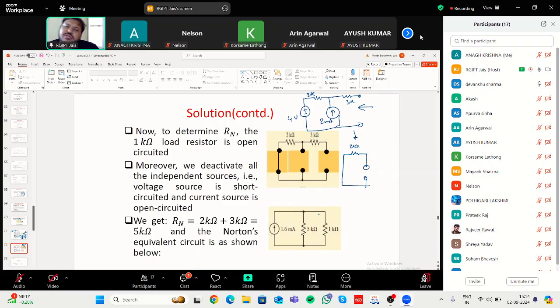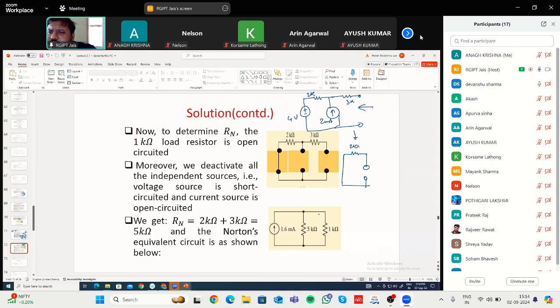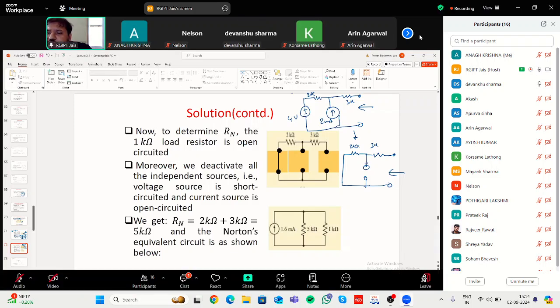Okay, you have to replace the current source, infinite resistance, so current source with an open circuit, and the resistance will be there, 3 kilo ohm, 3K, and these two are the terminals. So when you are looking into the terminal, what are you seeing? What is the net resistance? This part is of no use because no current will flow through this path.